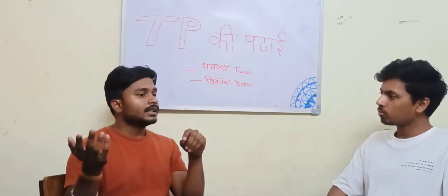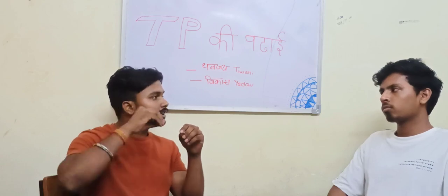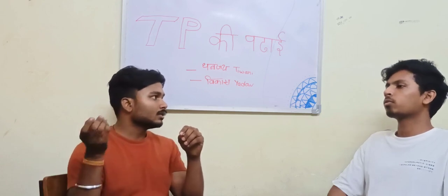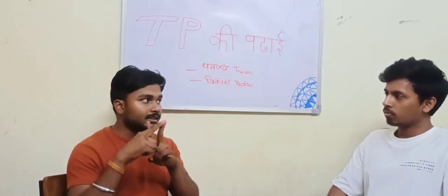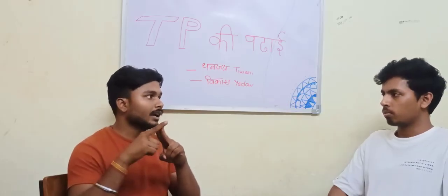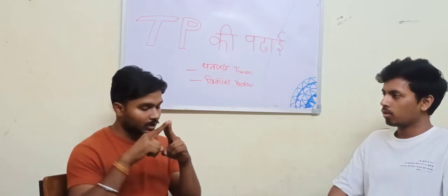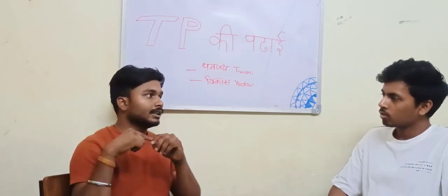We cannot take the velocity as greater because the residence time will be very low, so conversion will be low. So fluid velocity is the first parameter. Second is packing type and size, as we had discussed. And packing material plays a very vital role in that column. Third one is temperature difference, inlet temperature and the outlet temperature.